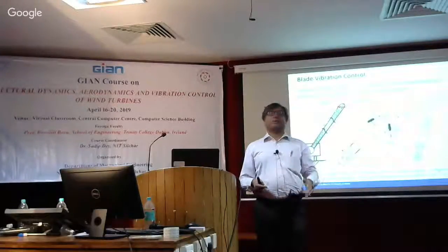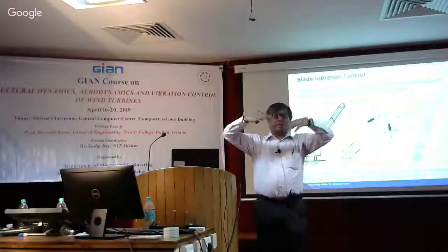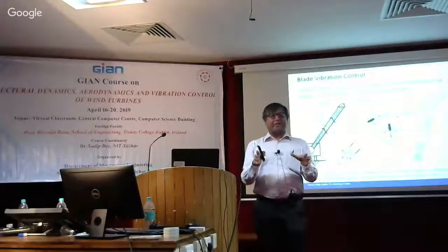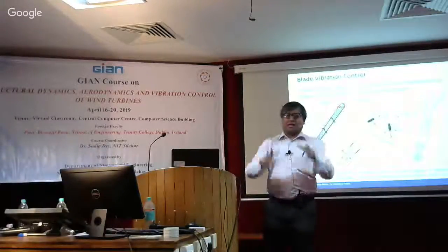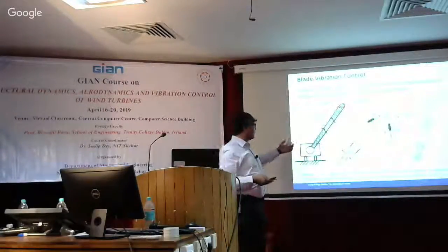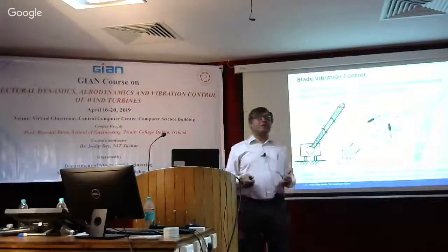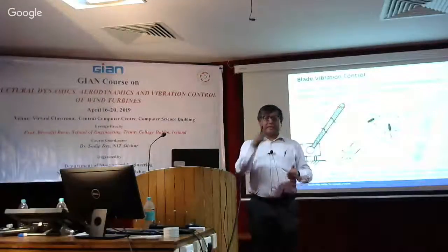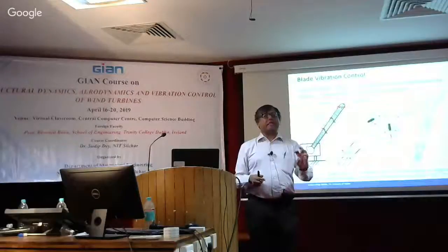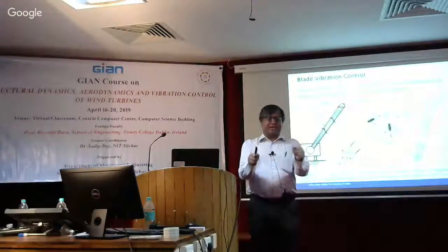So the way they construct the spacecraft would be, because the people who are working at the top have a lot of sensitive devices, they have to control the vibration actually. And they construct a kind of frame structure, tubular structure like this, and cross structure like this. And the control is done by means of stays or cables. And the cables are controlled by servo motors actually at the end. So the displacement is controlled by the tension of these cables.